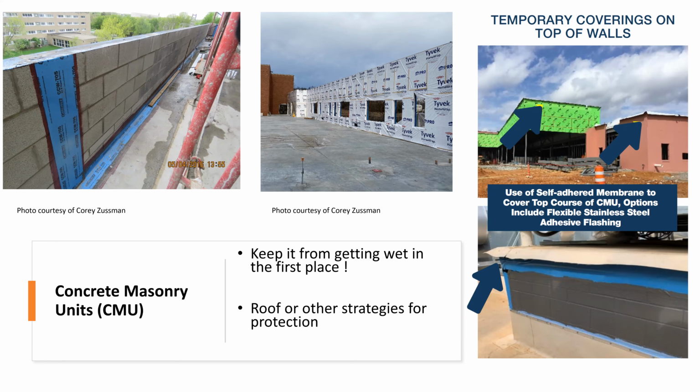So we've got protection at the top, we've got protection on the back side, and then the picture on the left is showing where we have a connection from a poured concrete to concrete CMU. Sometimes you get a rainstorm, and the concrete floor just gets tons of water. If it starts to hit that connection between the concrete masonry and the poured concrete, well, we have this little space that the water is going to get down. As it gets down, it's going to flow down the backside of the parapet and make those concrete masonry units wet. So, if it's not raining, great.